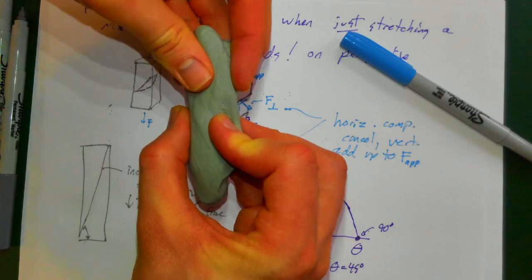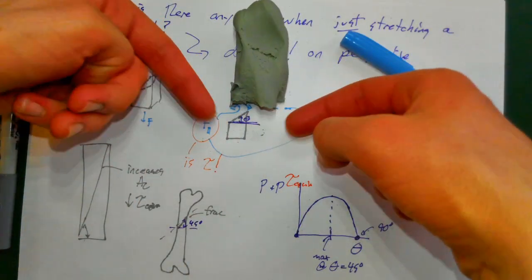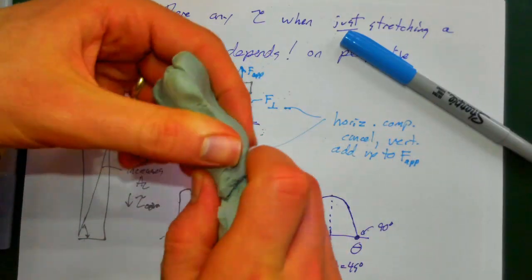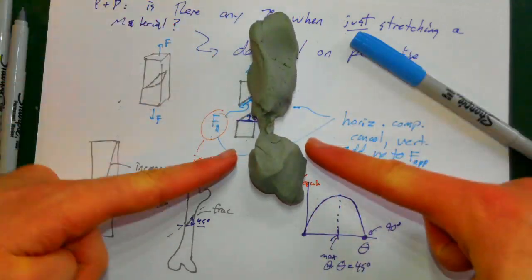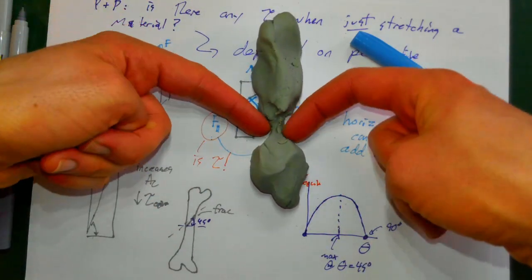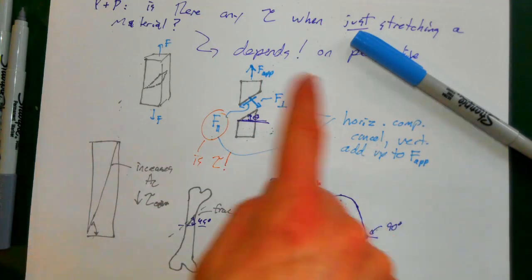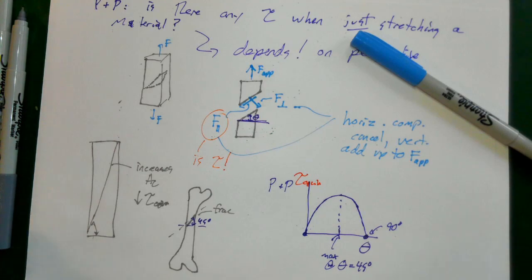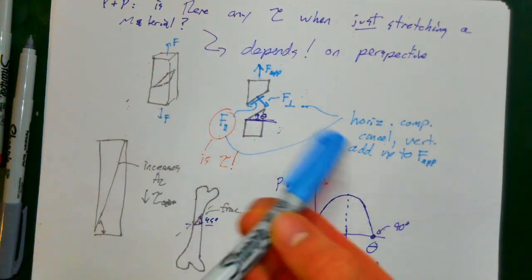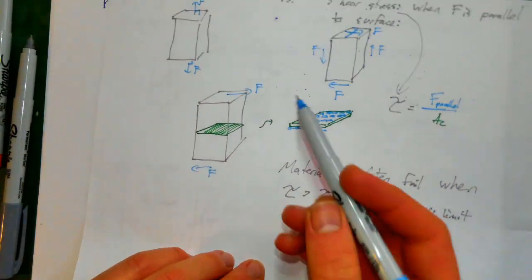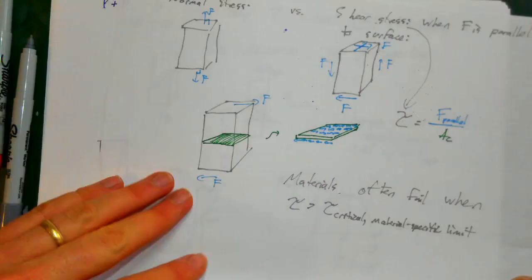45-degree fracture lines for bone breaks, and when we physically test materials in a materials testing machine and stretch them out, oftentimes what you'll see, not for Play-Doh, because Play-Doh is a little bit weird, but for a lot of other materials, you'll see it neck down into this kind of 45-degree cone that eventually meets at the middle and the material breaks apart. So it's not magic. Shear stress can actually appear even when we didn't really apply forces in this strictly shear stress seeming phenomenon.